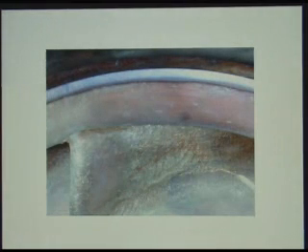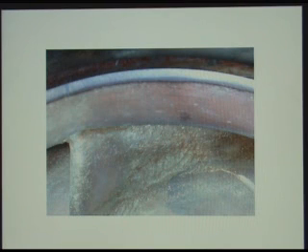Well, as that vapor bubble collapses, it goes from a very large area to a very, very small area. And when it finally collapses up against the edge of the impeller, that very small area of collapse causes a very high localized stress on the surface of the impeller, which causes pitting. And if it goes on long enough, you end up having a severe amount of pitting on the impeller and any other place the cavitation occurs. Obviously, since our hydraulic passageway is no longer smooth and we no longer are going to have laminar flow, we are going to increase the losses inside the pump, and so the pump will not be as efficient as it originally had been.